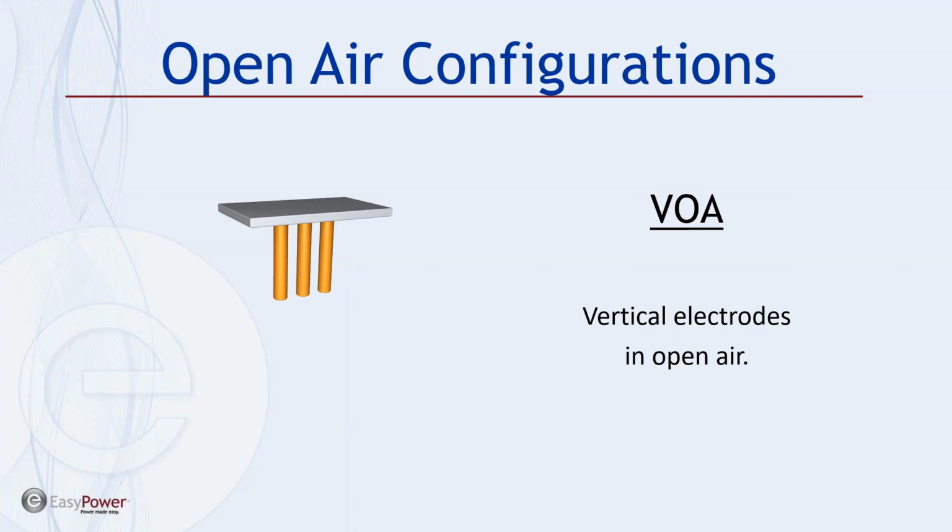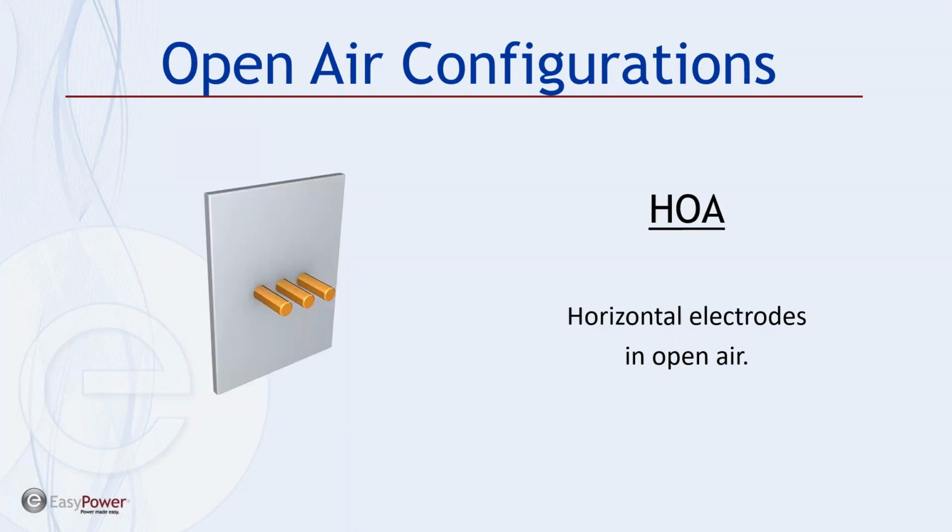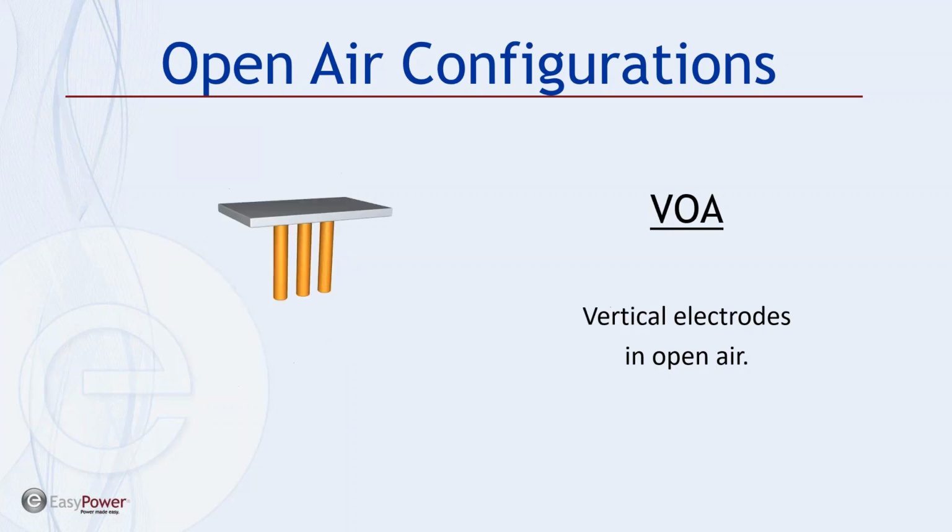Again, more because of the operator proximity rather than what the termination is actually doing. So again, this is set up because radiation is coming out straight at the operator, and in the other case the incident energy is being radiated down more so, and the operator standing to the side has some exposure, but it's not as much as if they were directly in the path of the termination.